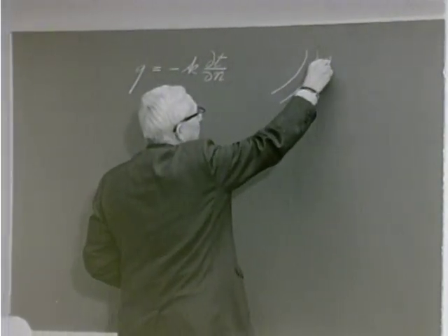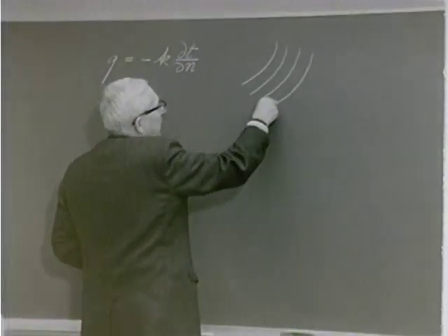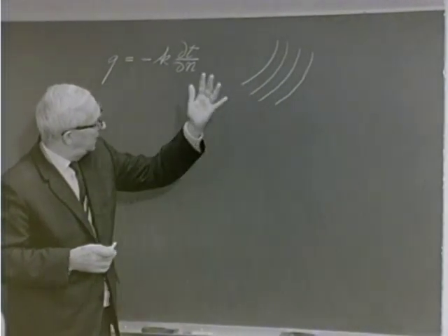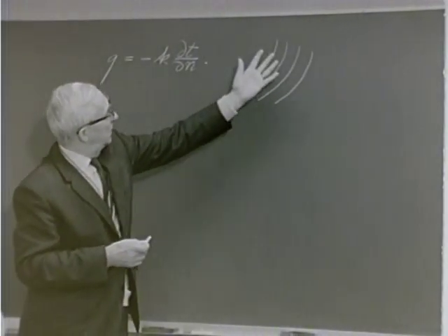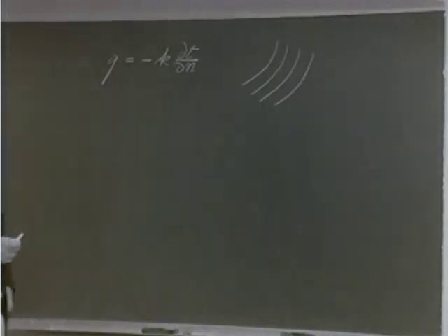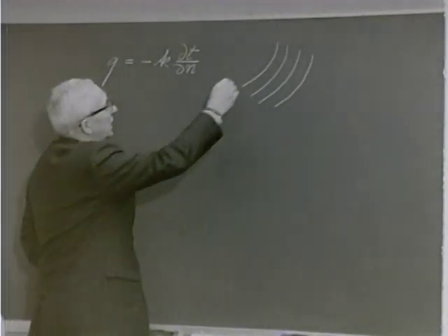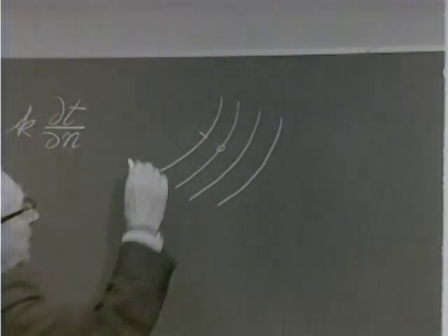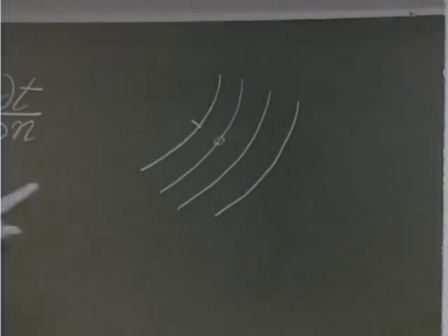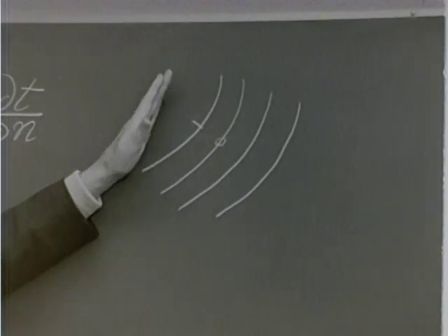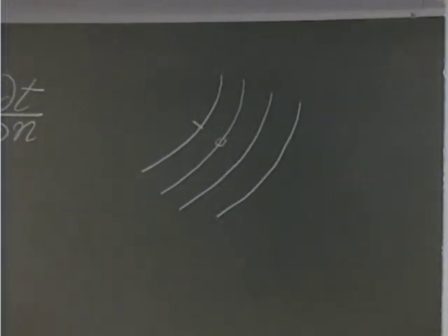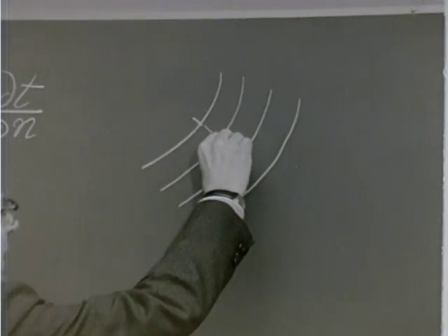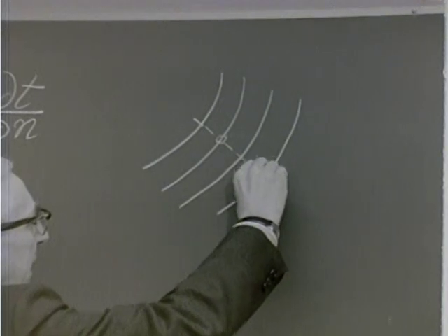So we have some surfaces which are isothermal surfaces, which in a two-dimensional case would be the same at any cross section parallel to the blackboard. We could select a point, and we want to calculate with this equation the heat flux at this time, where this picture represents our isotherms. Then we find a heat flow line which is normal to the isothermal surfaces.